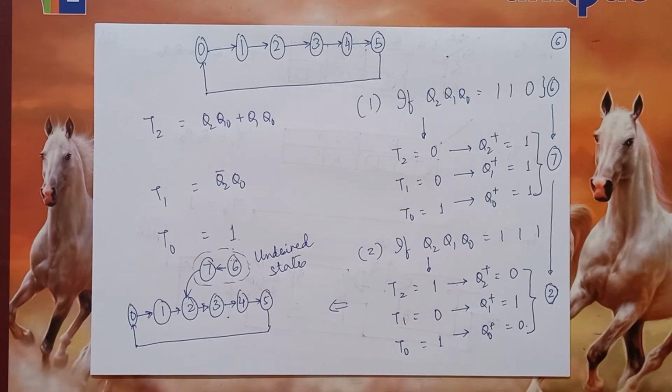So, while using don't cares for the next state in case of the undesired states helps us in reducing the additional logic complexity that is needed, there is a danger where we initially do not know what will be the next state of operation if any undesired state comes.